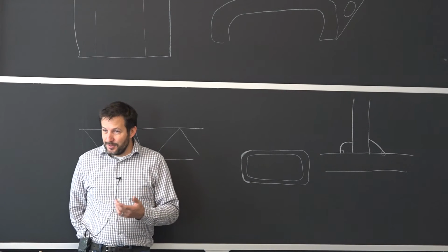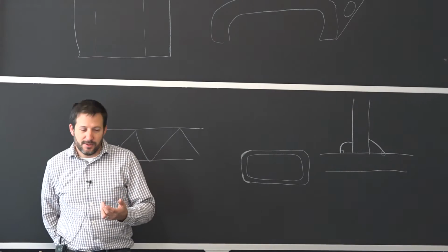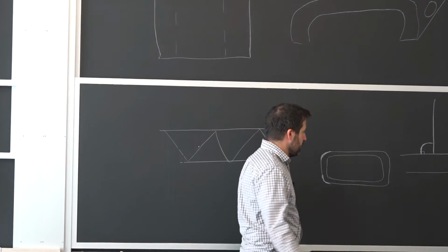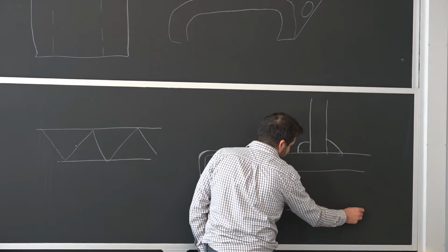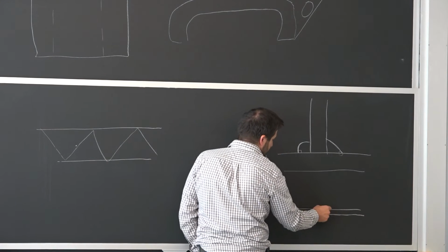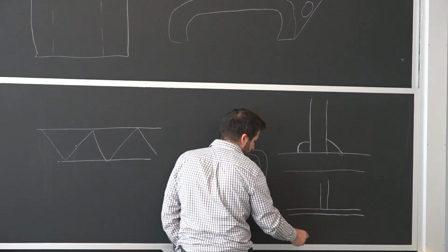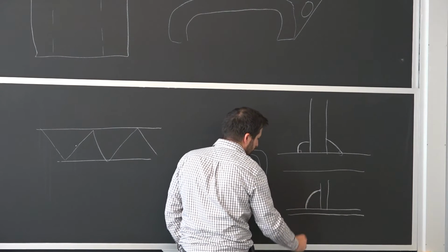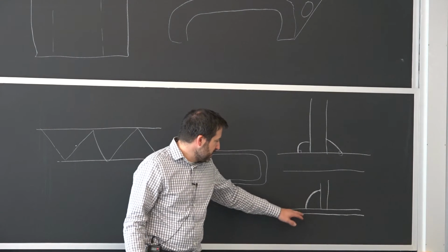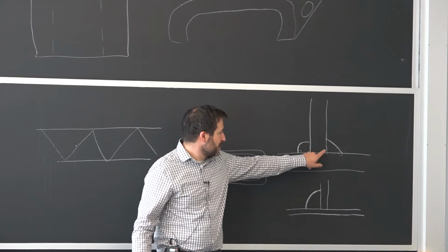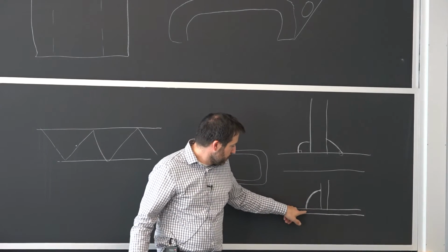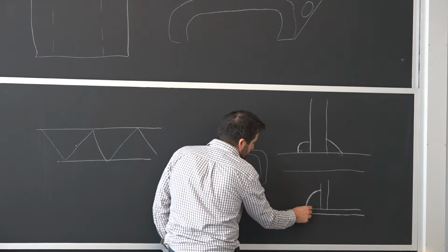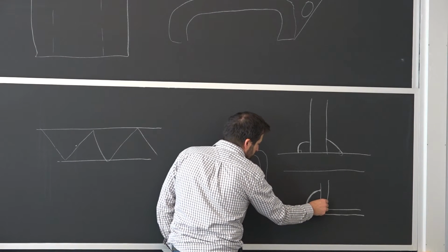Now, I don't want you to get too scared. So if you go to the gym and you see the equipment there, a lot of times what you're faced with is relatively thin material. So let's say there's a tube, any weightlifting stuff, and then you have this big bead that almost looks like it's not fused. Okay, so what happens here is if they melted and tried to do something like that, they will perforate all the way through the base material. So they need to be limiting the fusion to something like this.